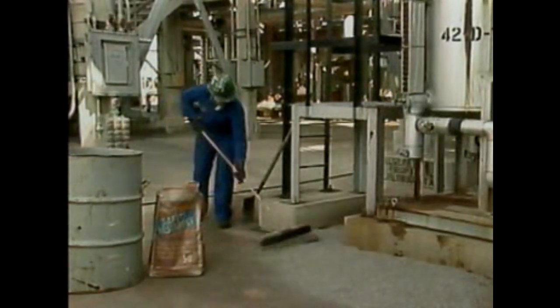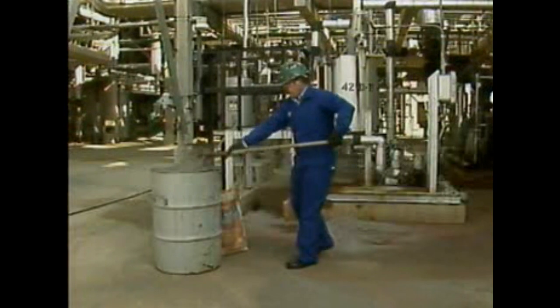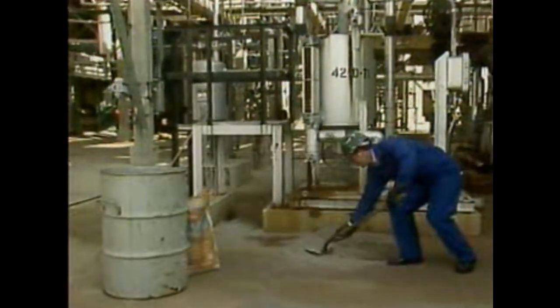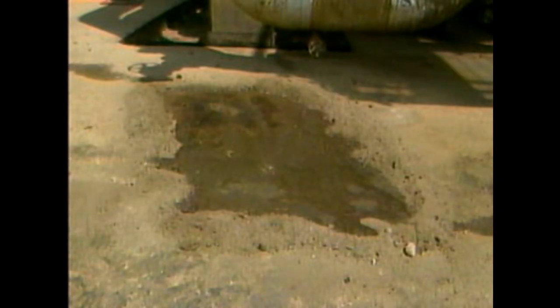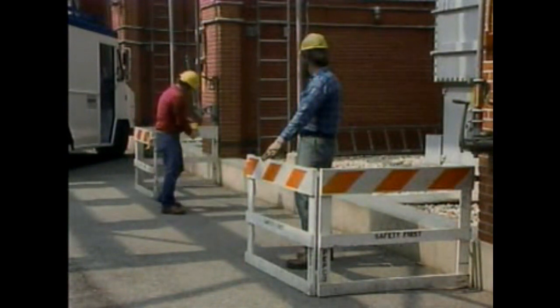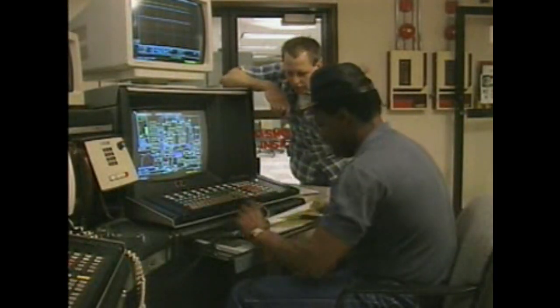Again, it's crucial to know the chemical. Even a small spill could result in fire, a violent reaction with another chemical, or a release of dangerous gas. If the nature of the hazard doesn't require an immediate exit, make sure that you know your facility's procedure for handling the situation. Generally, the response to such a hazard includes blocking off or marking the area and notifying appropriate personnel.